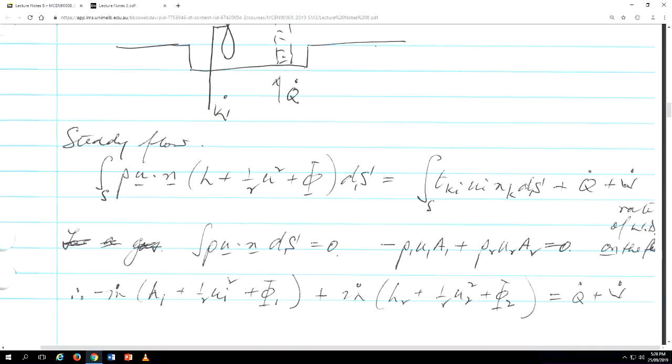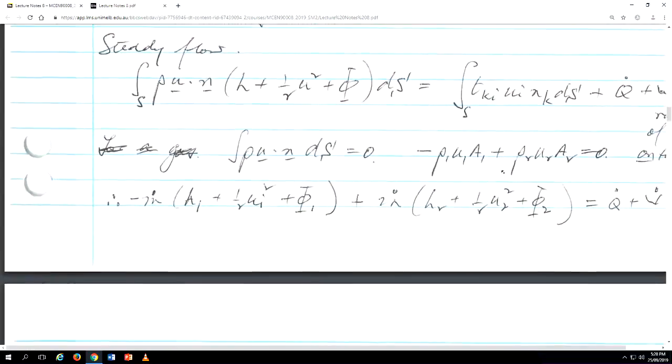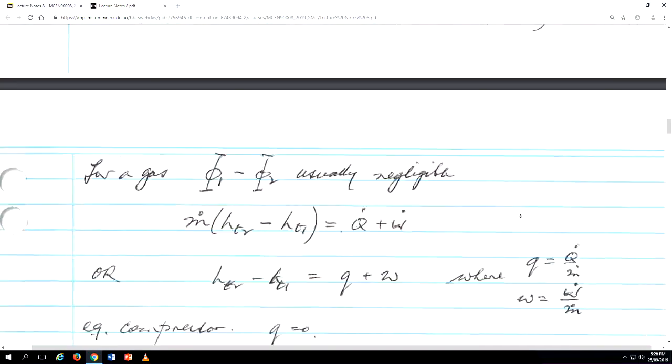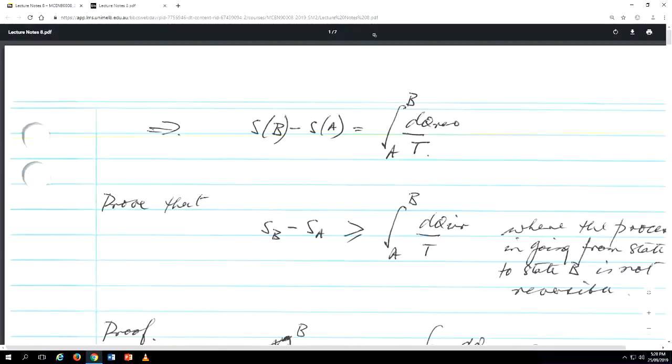All right. For unsteady compressible flows, would that term also tend to zero? It wouldn't be on the normal boundaries, no. Well, it could be, because the du/dx could still be zero. That's to say, if I had constant area and there's no change in the velocity where I drew this boundary, then tau_xx would again be zero, because it's 2 mu du/dx.